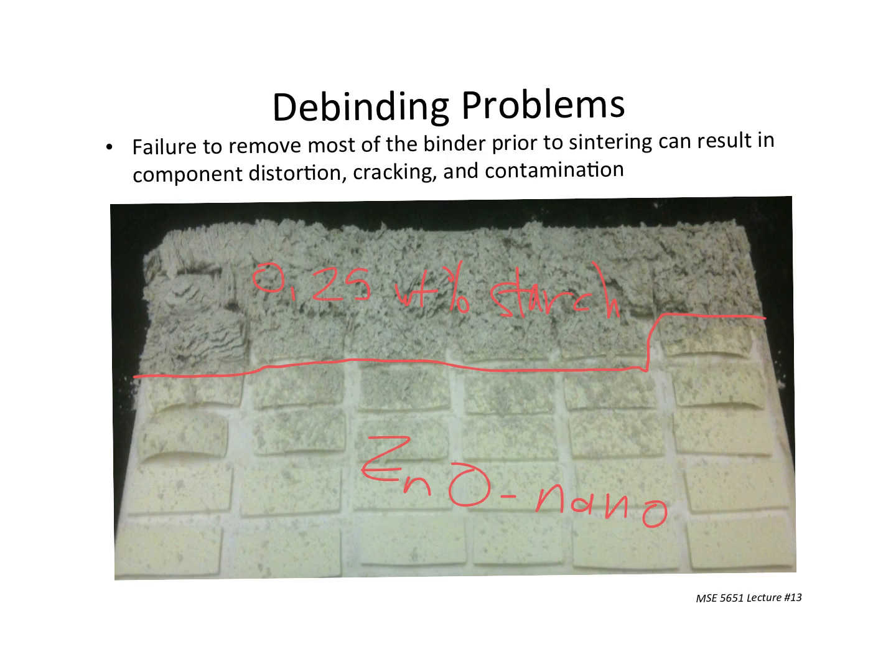So this is a reasonable additive that was added to try to provide some additional strength during the compaction process. And the heating rate was also, which is very important, 2 degrees C per minute. So not extremely slow, certainly not extremely fast though. What you see here in this upper portion, first of all, the lower portion looks fine, and I should also point out this is going to 500 C. Not very high temperatures, just enough to burn out the organic, more or less. That was the whole point of it. And then we'd switch to a different furnace and complete sintering there.